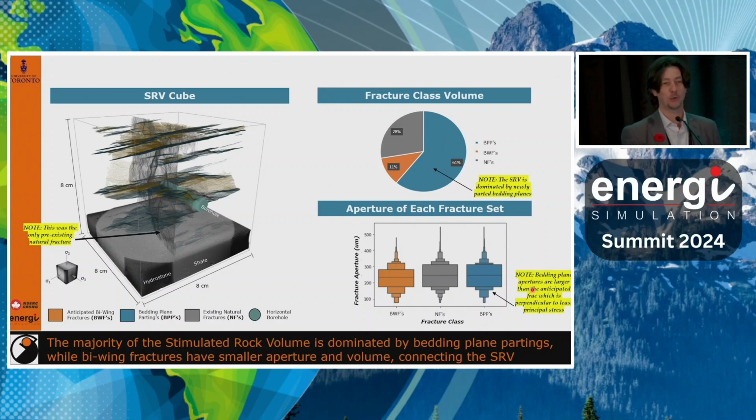So the joke was, well, probably the rock didn't go to school and didn't learn about that, but it was consistently fracturing in a different way. And parting of bedding planes, so parting along those finely laminated planes that are common to any unconventional reservoir, was key.